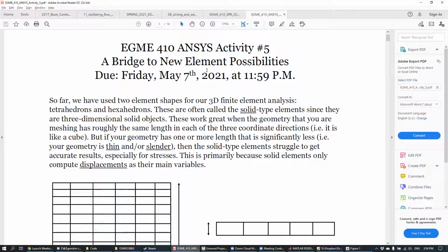Professor. What's up? I had a couple questions. So in the weak form of the 1D elasticity equation, I was confused as to what you would plug in for A of 0 and W of 0. I know that it depends on where the traction boundary condition is on the domain, if it's where x equals 0, x equals L. But I was just confused as to what W of 0 and A of 0 would be for those situations.